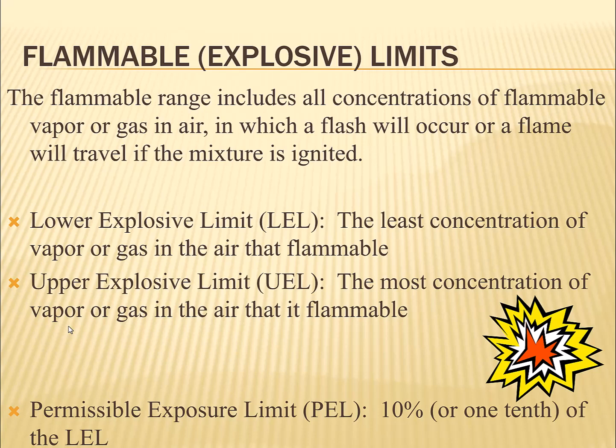Well, here's the thing, it's very hard to measure accurately the lower explosive limit or the upper explosive limit, because these gases have a certain buoyancy level and they can move around in the air. So they could conceivably have a higher concentration on one side of the room than the other, where you could have maybe too much up at the very top, not enough down at the very bottom of a tank or inside a shop or inside a room. And then somewhere in the middle, you have the right concentration.